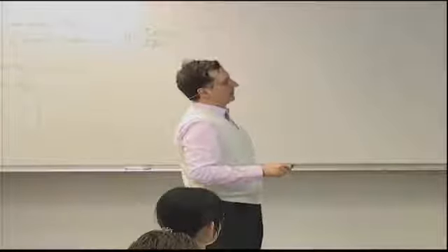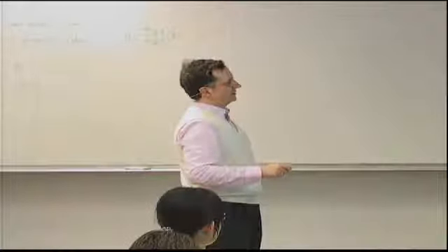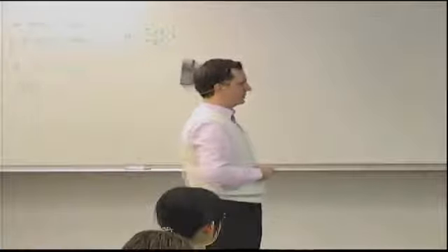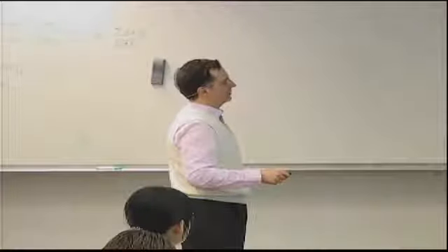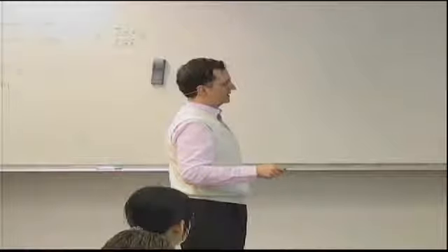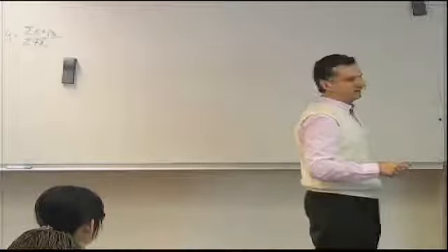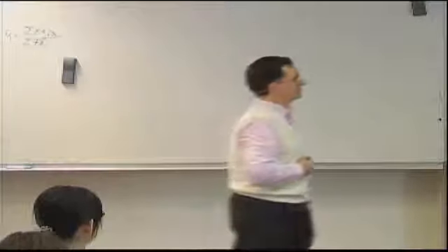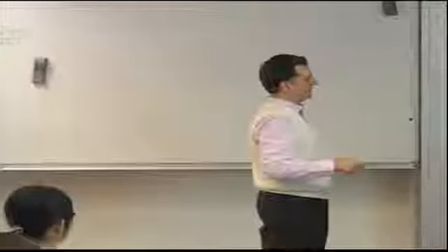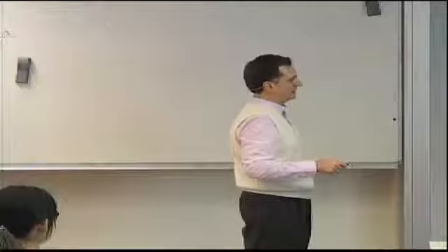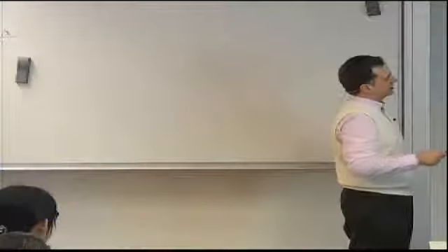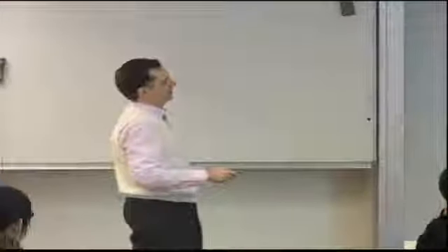The skin properties, D matrix, should be times 100, so these values are 100 times smaller than what they should be. But anyway, these are the properties for the skin. The skin thickness is 0.57. The A matrix is here, and for the stiffener, the dimensions are what we arrived at last time. We revisited this stiffener design in terms of the B's and the T's. B's are the length or width of each member, and T is the thickness. For the stacking sequence we have so far selected, not necessarily the best possible, the corresponding membrane and bending stiffnesses are shown in the last 2 columns.